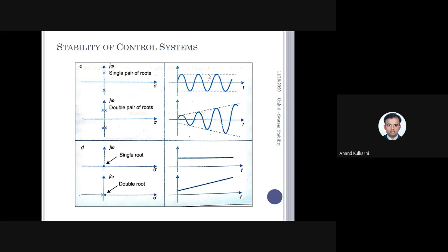First law of stability: if the input is bounded, output is bounded. So when the input is bounded, output remains within the bound. But in the absence of input, output should tend to zero. It is not tending to zero. So it is following the first condition of stability, but it is not following the second condition of stability. So this system is neither stable nor totally unstable. In that case, it is called limitedly stable.